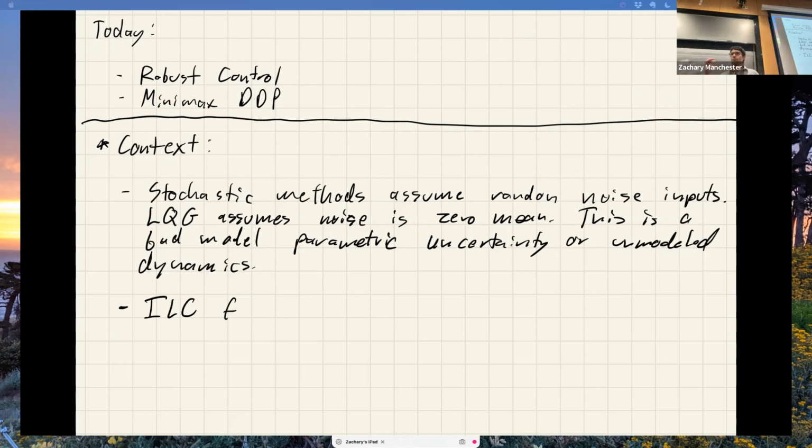I'm going to do some data-driven stuff, run some rollouts on the hardware, and adapt my control policy to the specific parameters of that robot, right? That's adaptation. If I take that and run it on another robot that has slightly different parameters, but it was dialed in on a different piece of hardware, it could just blow up on the new robot, right?